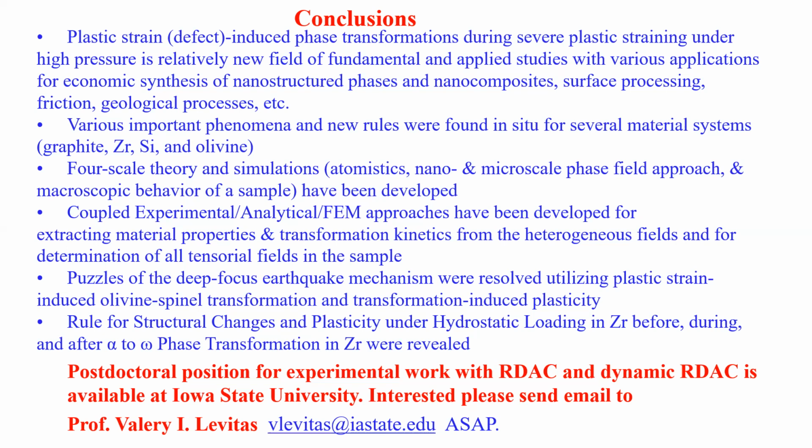Thank you for a very interesting talk. Is there some critical criterion for the transition? Is it possible to somehow define the criterion during the deformation? Well, at different scales, the criterion looks different. I don't use the concept of critical energy here, but a combination of stresses. Are you talking about a perfect crystal or a real material? For a perfect crystal, I'm talking about a combination of all components of the stress tensor which cause phase transformation. We can introduce a generalized Gibbs energy, but it's not very clean. It depends on the path for large strain formulation, which is why I try to avoid this. We have this in papers, but it's more straightforward to use a combination of stresses.